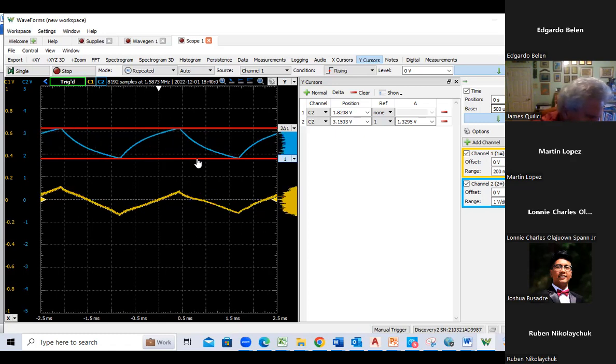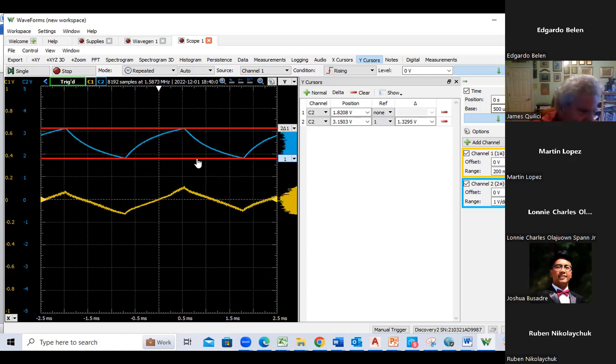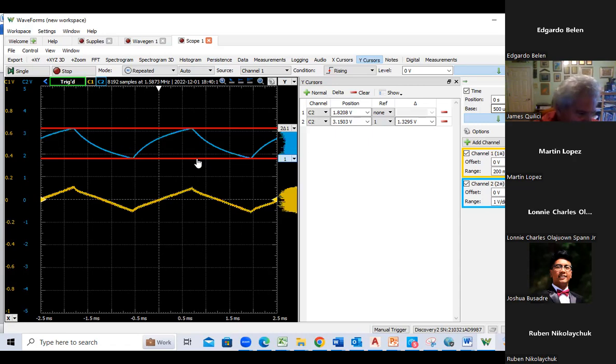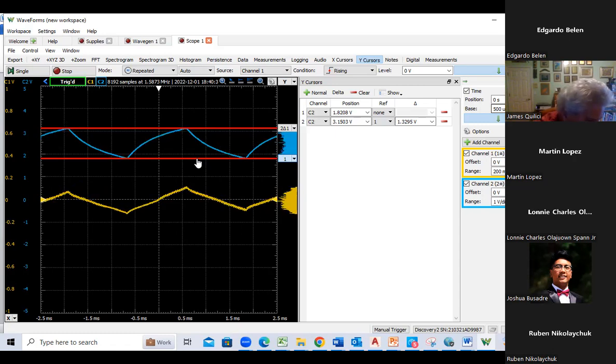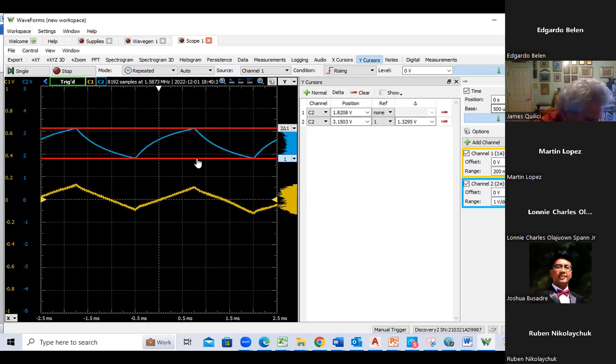For the temperature, if I was in a lab building a circuit, we basically have heat guns, or essentially a hair dryer. If you blow that on your circuit and the amplitude doesn't change significantly, then you know it's got some stability against temperature variations. And then the beta, I don't know. I'm drawing a blank on that right now.